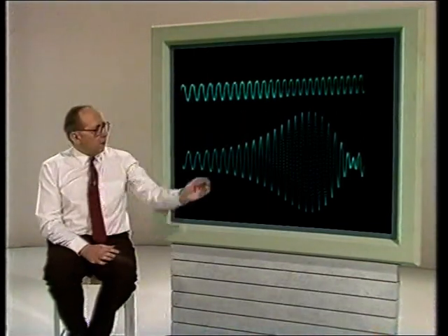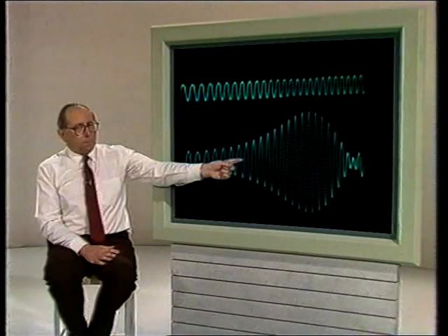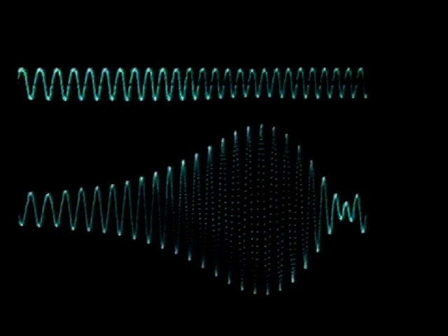And below, the output response. The output amplitude increases rapidly with frequency up to a peak and then dies away again. This peak is associated with the rather extreme oscillations you saw and is characteristic of a phenomenon called resonance. It's a condition which designers try very hard to avoid. In fact, this peak occurs at a particular frequency for a given vibrating system. And that frequency is called the resonance frequency of the system.